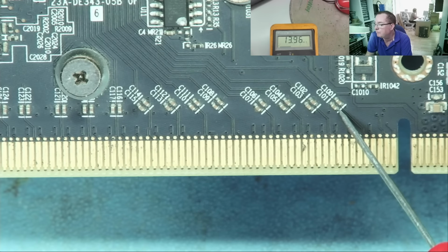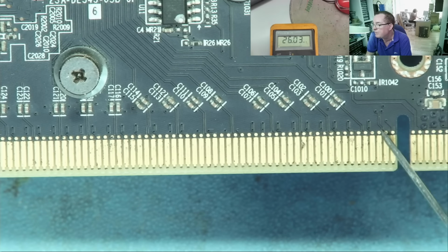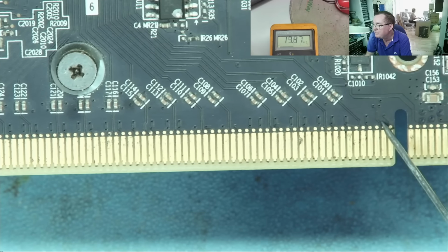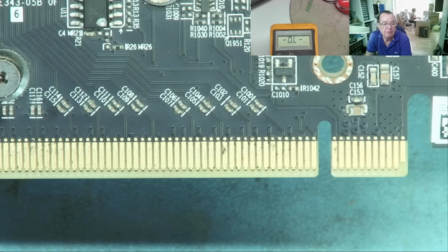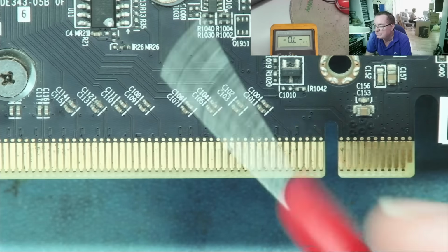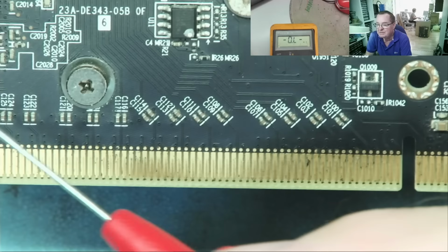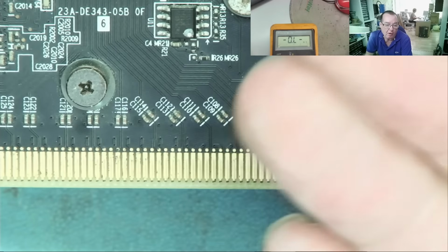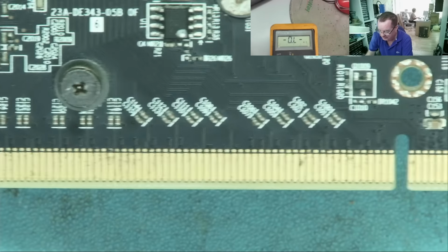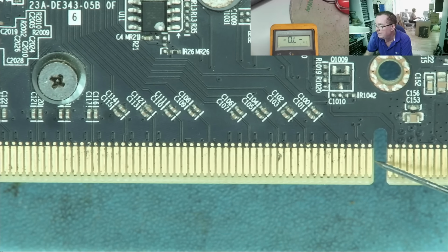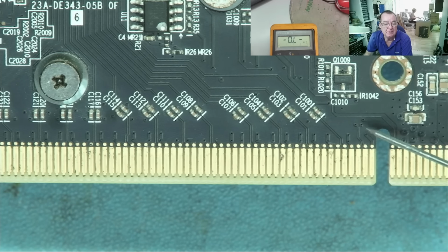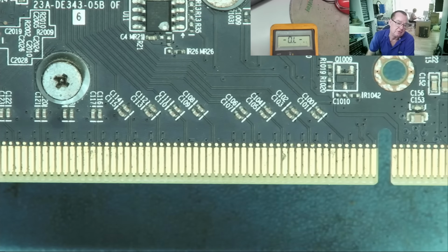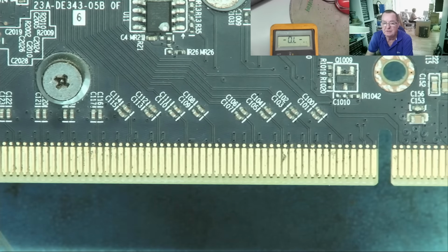Okay, but look, this one has another lane there on the second and third pin. Can you see it? It goes through the board just here, yeah? So it looks like this side has 17 lanes. It doesn't. It has 16 lanes, or half a lane, because the other half is on the other side. And this one is actually the clock. So this runs at 100 megahertz, and this synchronizes all the data transmission on the lanes.